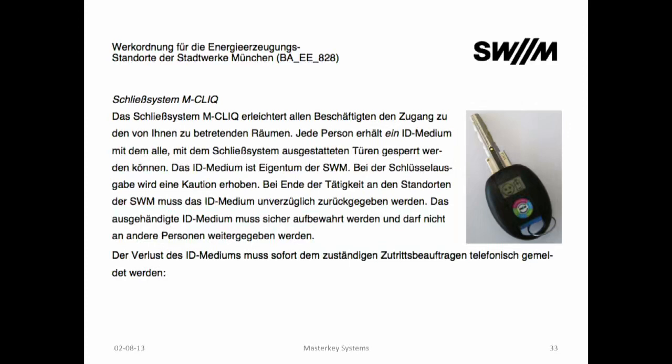But also this is the original key with this mechanical bitting. You can read out the mechanical bitting from its homepage. On the web page, you find the mechanical key as a PDF file. So the first step for making a key for the new system is already here. Okay, you see the complete mechanical bitting of this key. So I can cut this key, so I only have the electronic part left.